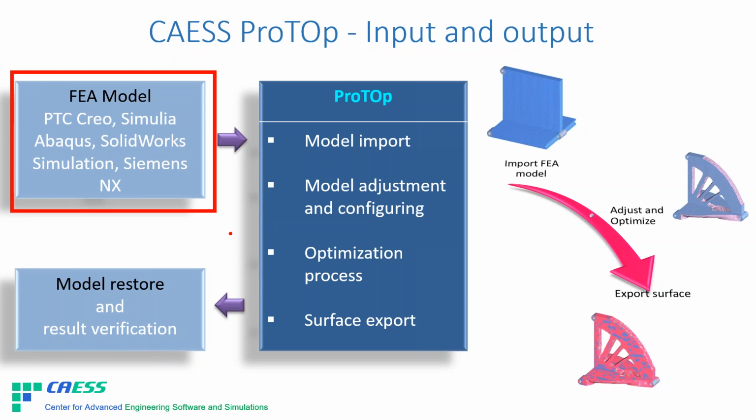The input that it gets is a usual FEA model, and what it produces is a design that, if you made everything correctly, exhibits lower stresses and no stress concentrations. So I wouldn't see it as a post-processor. Don't get the wrong idea. This is a designer tool.